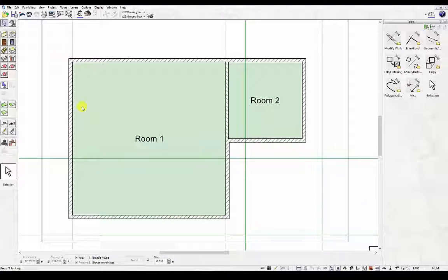In the previous tutorial we demonstrated how to place individual walls. In this next tutorial we will now place an internal wall using the placement method wall midway. This allows you to draw in a wall halfway between 2 points.